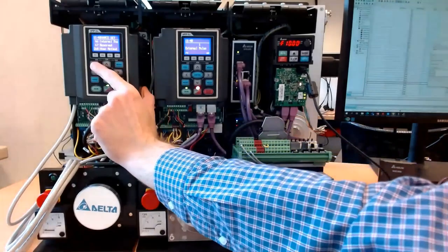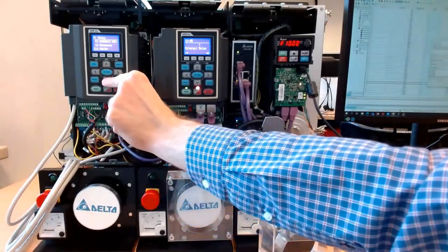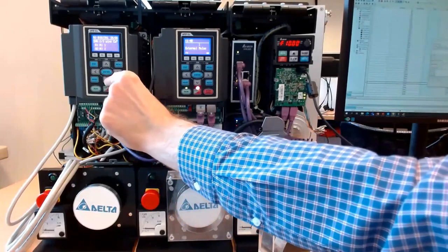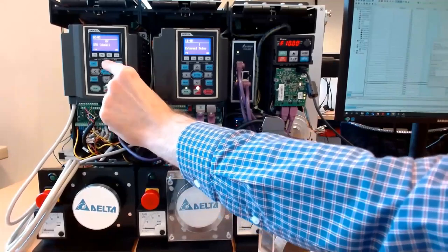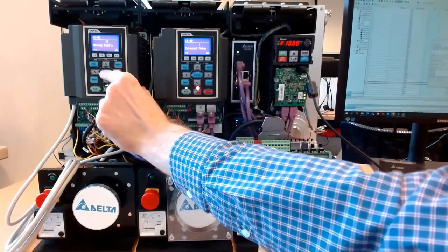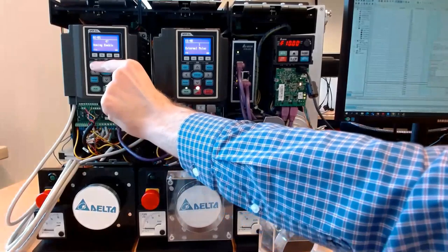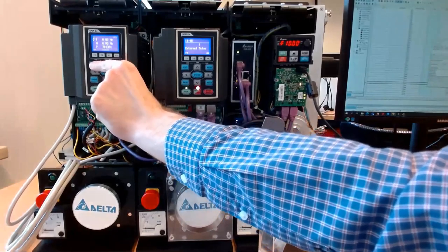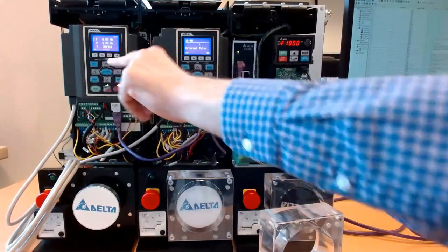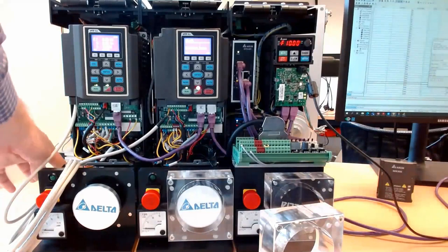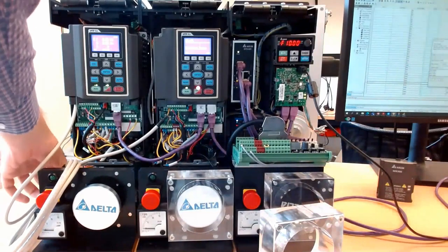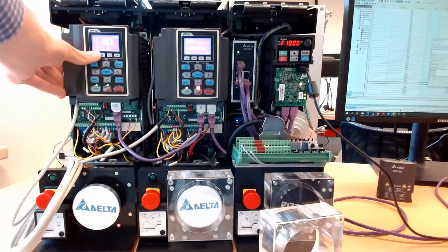I can also program one digital input to start the homing. So for instance, MI1, if I set this to 47, then this enables homing. When I trigger MI1, you should see the position of the drive switch back to 0. So firstly, I'm going to give it a servo on. And then I have a digital input over here. Yeah, and you can see the position switching to 0. Okay.